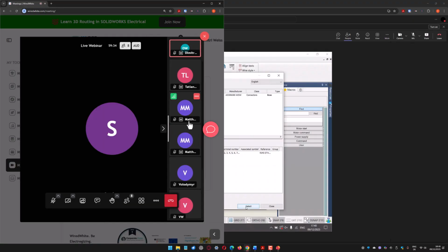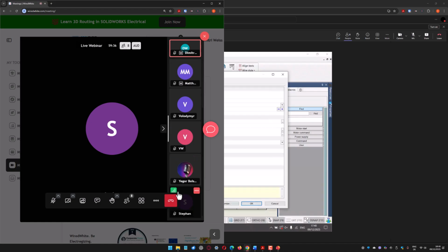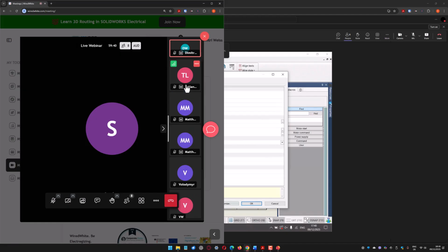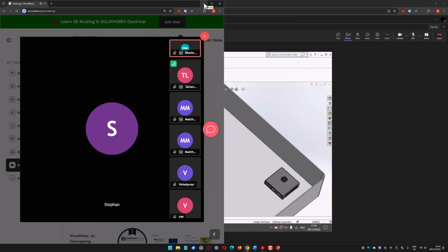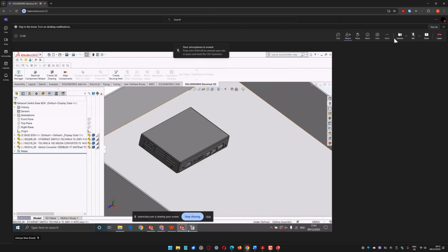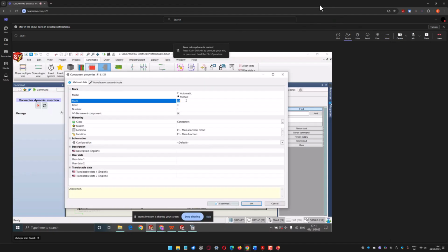And then once we select this, it will give me the option to create the reference name for it, like for our Ethernet switch. This can be port 1, this can be port 2, and we have to name these things beforehand. So I'll name this as RJ45 switch 1.